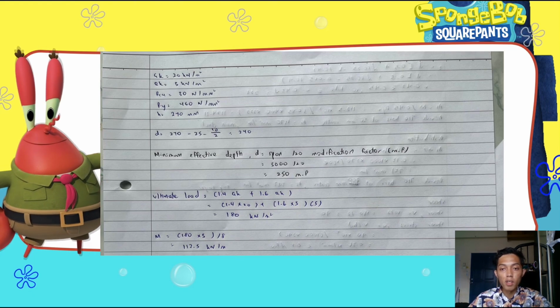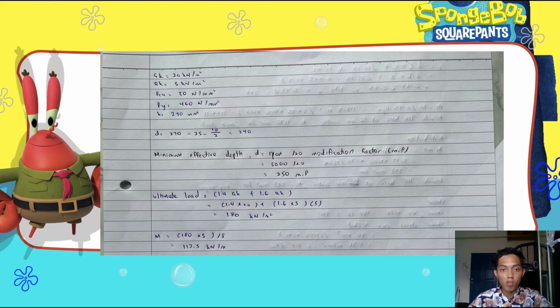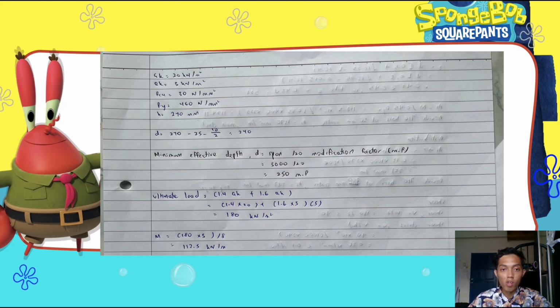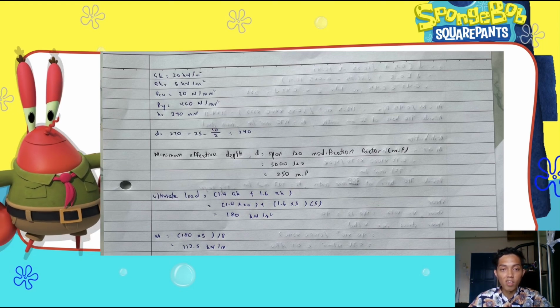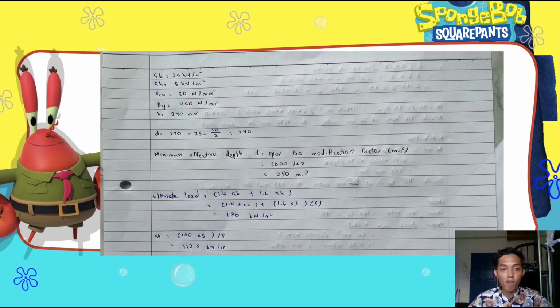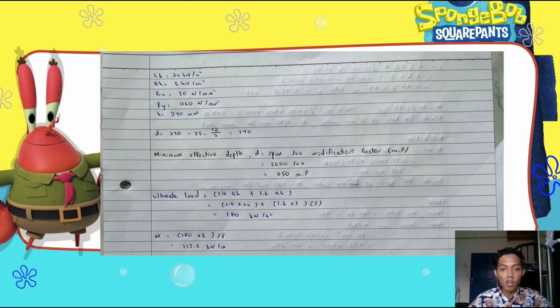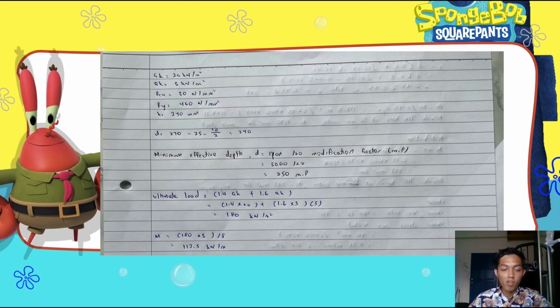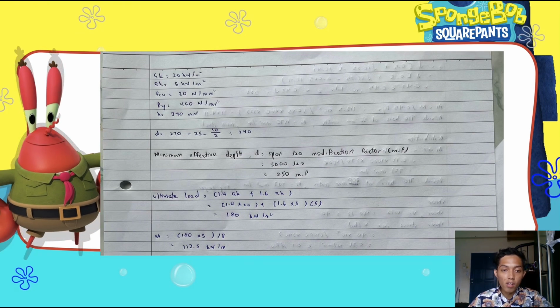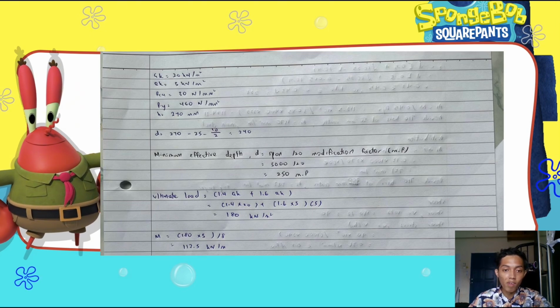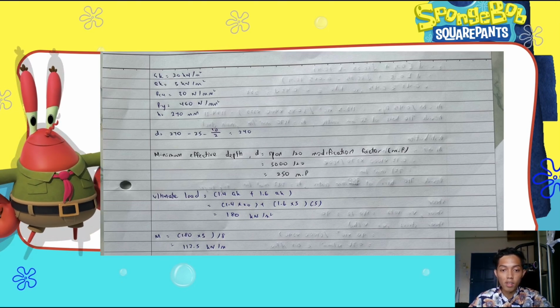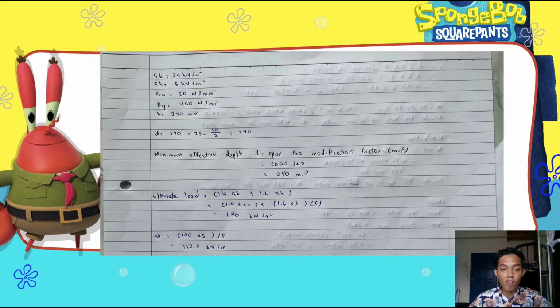Today I will be presenting my part, which is the slab. In this picture we have a dead load like what was given in the question, but unfortunately we must assume FCU, FY, and D. For this slide, we must find the minimum effective depth and get the answer. Secondly, we must find the ultimate load and we get the answer. And lastly, we must find the bending moment.